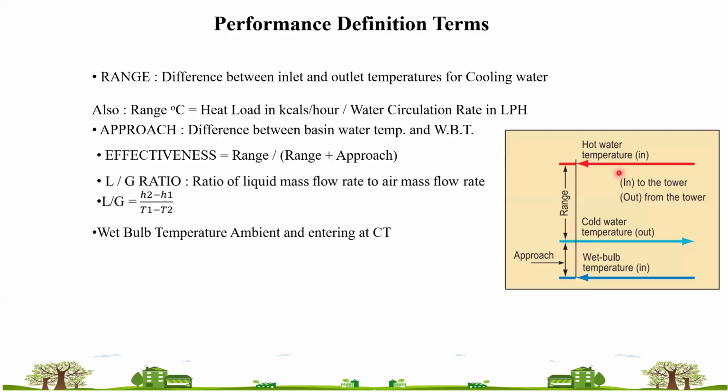So what happens in the chiller? Your chilled water is gaining some heat from the process or AHUs, and that chilled water is circulating in the evaporator. Heat is removed on the refrigerant side, where heat exchange happens between the refrigerant and the chilled water.